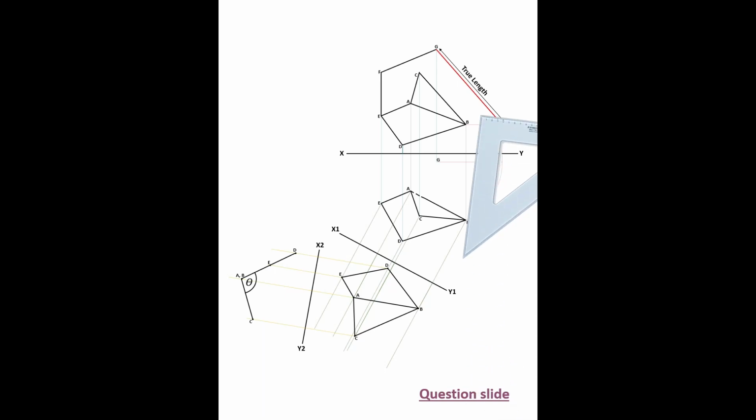All we have to do is repeat the process in the plan. So once again, we get our sliding set squares, line it up to A and D, and we just slide it up until it reaches G in the plan, and we just mark in our F lines. And that gives us our entire plan and elevation, fully completed. Right, so back to the question.